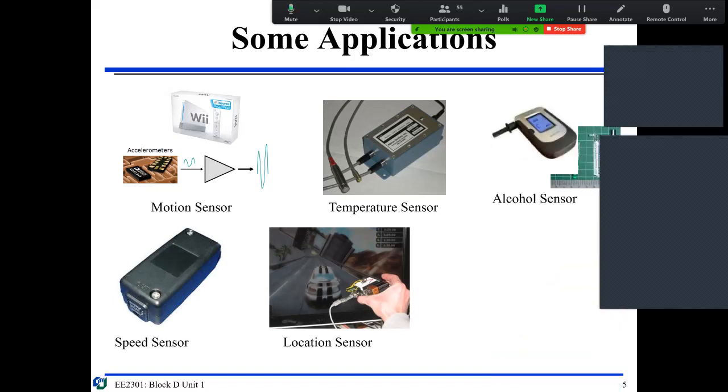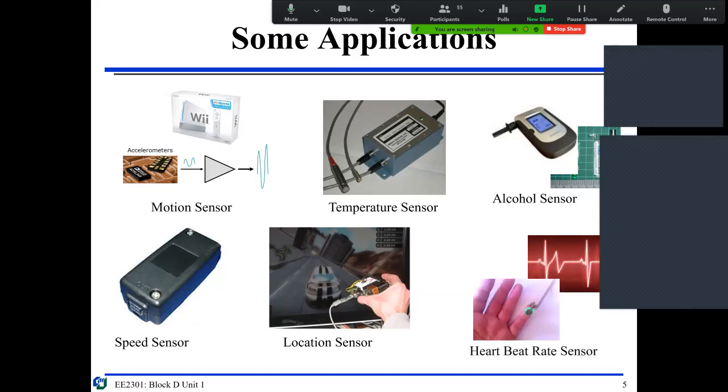If the police ask you to blow into the tube, you should. Don't refuse, okay. So the alcohol sensor also gives a very weak signal. Then you amplify it, visualize it, and convert it into the display, to see whether you are over the concentration. Of course, this is also useful for heartbeat. When you pick up the signal from your fingertip, it's actually very weak. So you need to amplify it. So all these need amplification.